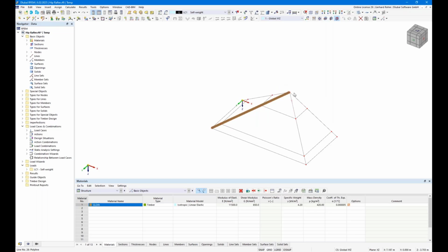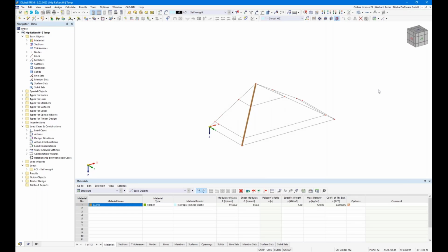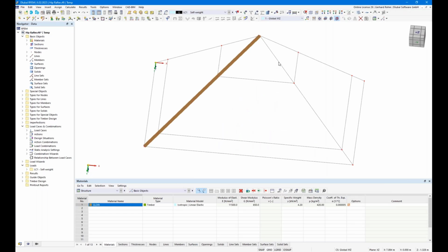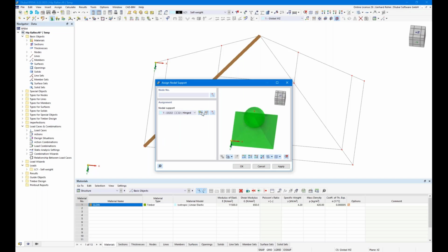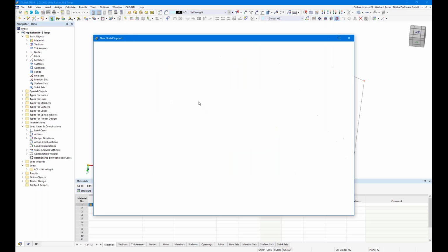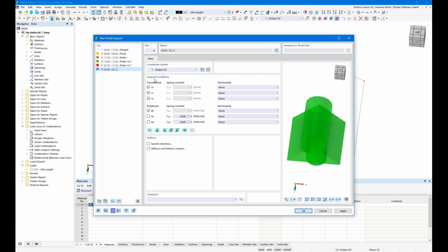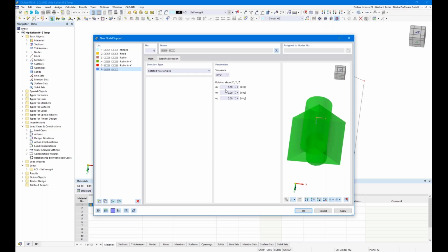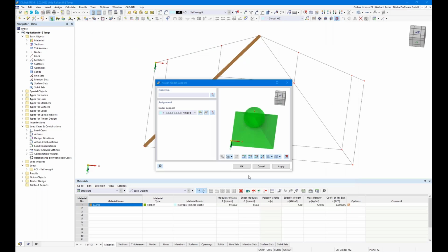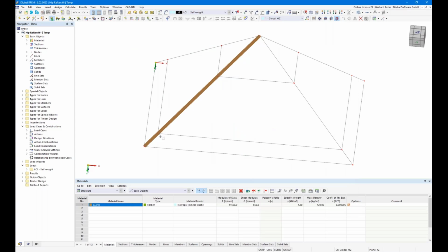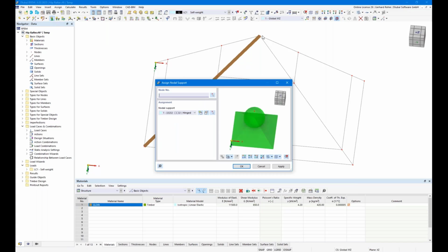I don't want to have the beam also here because it's symmetric. So I just added this to the structure to show you what is possible with the loads and so on for later. Okay, then of course we have the beam, we need support. So I create just 2 nodal supports. Of course, I need to rotate the supports by -45 degrees in this example. So I fix support on the bottom and the sliding support here on the top side.